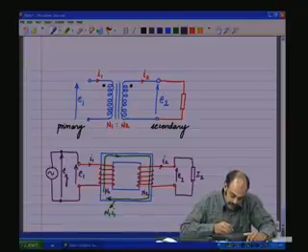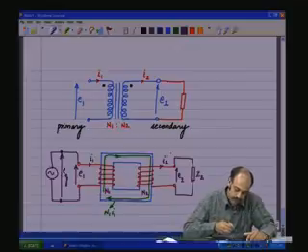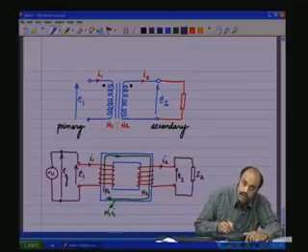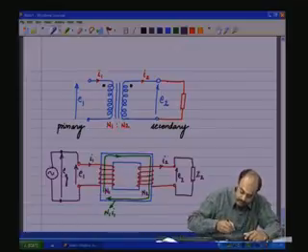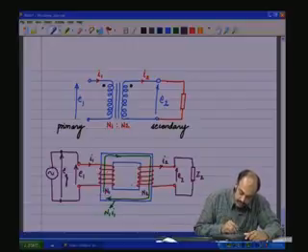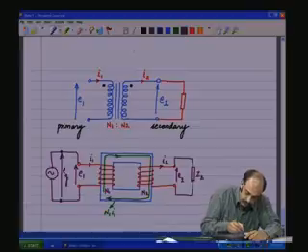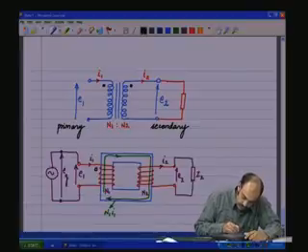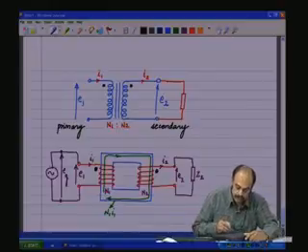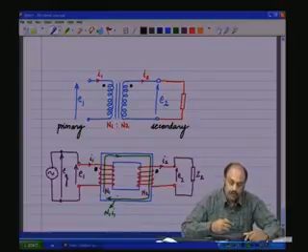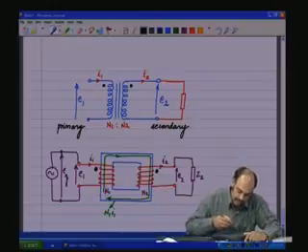Now, this current is flowing through this coil, which is going to provide a cancelling motive force. So, MMF is provided here plus minus, let us say here at a given instant. Now, a current flowing out of the dot, isn't it? Let me put the dot. The current is entering the dot, current is flowing out of the dot, is going to create a cancelling MMF.